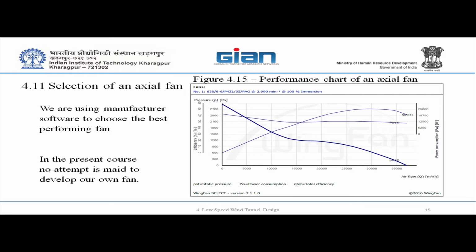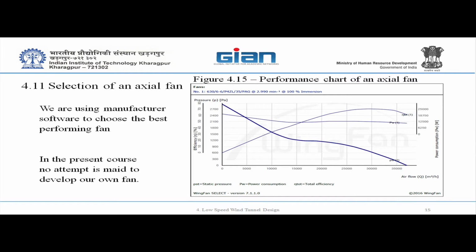I'm not sure, because anyway you have an adverse pressure against which the fan is working, because the fan is creating its own pressure, right? Yes. But a bit upstream of the fan, if you have a diffuser, then the flow will see some extra resistance while getting accelerated. I'm saying on the contrary, because the pressure you're talking about is negative, and once you have a diffuser, the pressure is increasing. So it's decreasing the negative pressure that you have to suck. You have to work against a lower absolute value. That's what I'm saying.